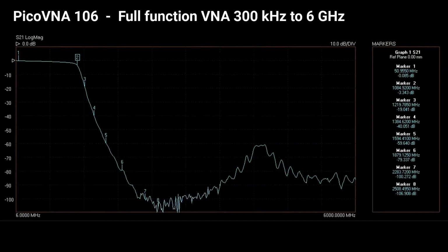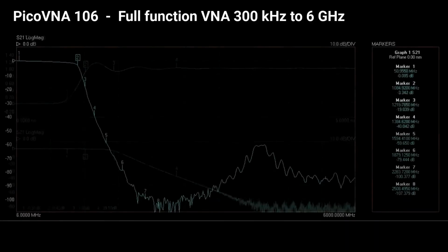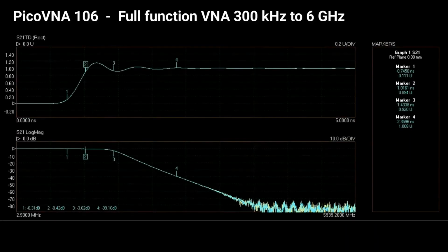and likewise there's no performance compromise either. This is a low pass filter measurement at 100 Hz bandwidth. No average or smoothing applied here. I have speeded things up a bit here to show you the trace noise and the marker noise over the dynamic range of the instrument, typically down to -118 dB RMS. Performance and value doesn't stop there either. Typically a $2,000 option, Pico includes time domain measurement at the single price.